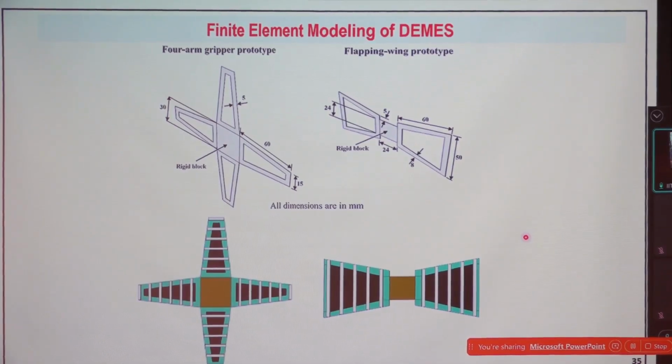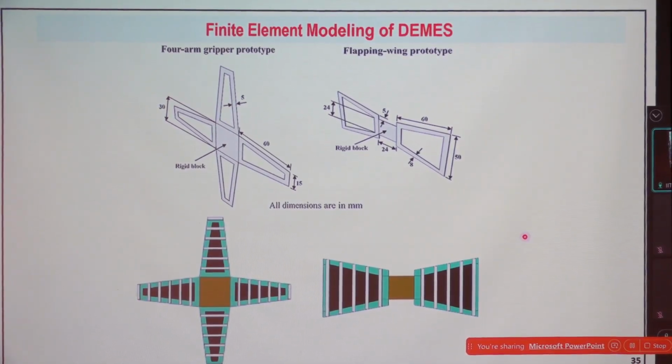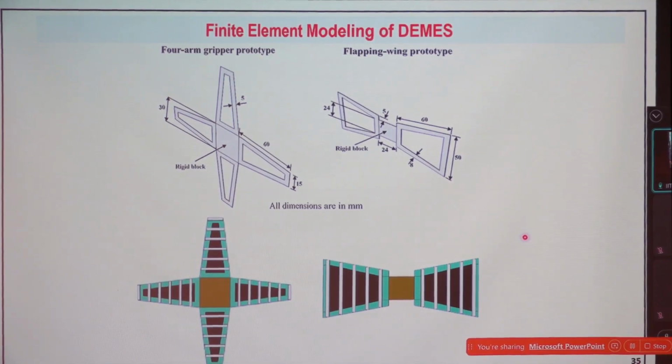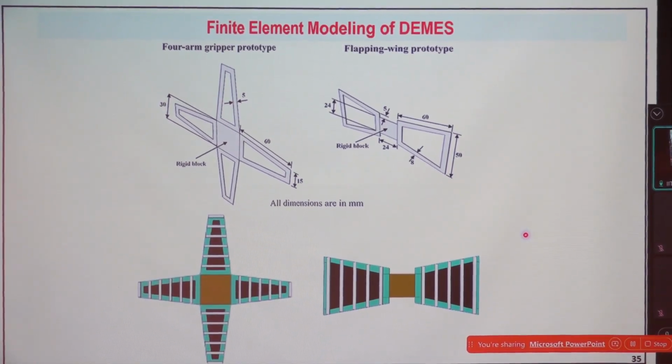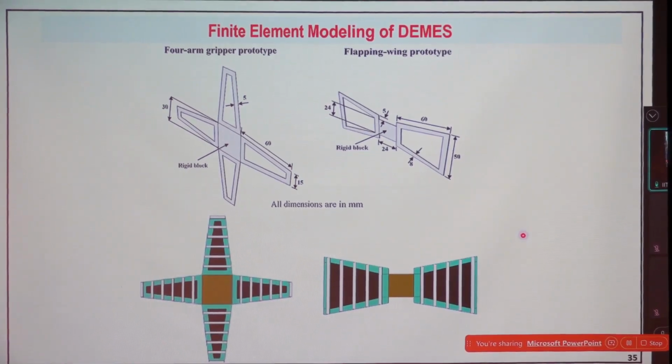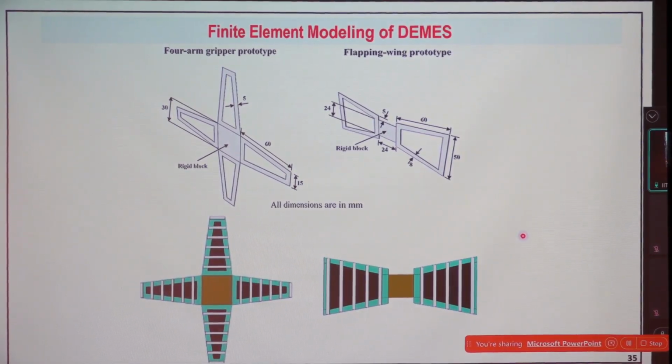Step 1 and step 2 are easy. Define the geometry and material property, carry out the simple simulation, get the principal stress and incorporate it. The third step is very, very tedious, and it's not that easy in Abaqus. You have to link Parallel Studio. The coding that I have shown you has to be done in C language basically, so you need knowledge of C and how to implement that. Parallel Studio basically connects Abaqus with the constitutive model in C, the formulation and C programming that we are doing. So 3 different things you have to couple together.